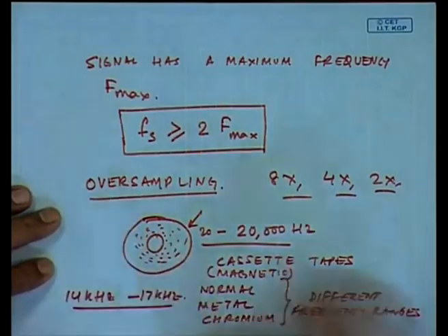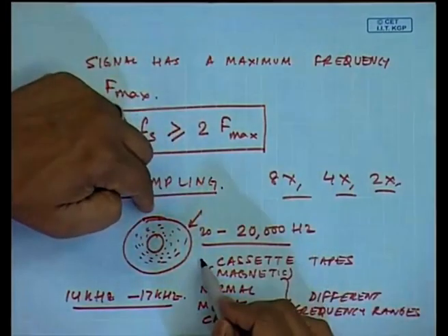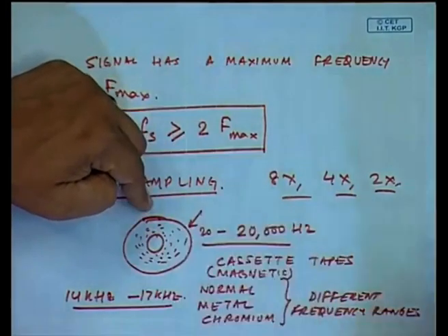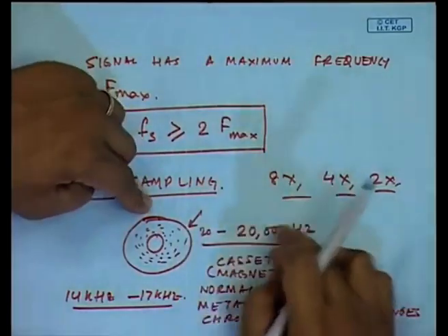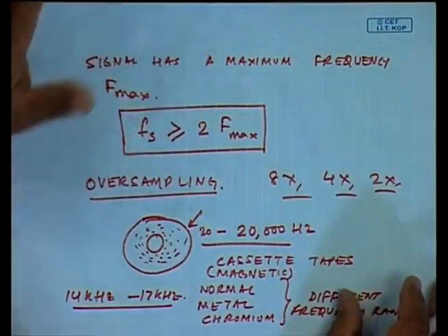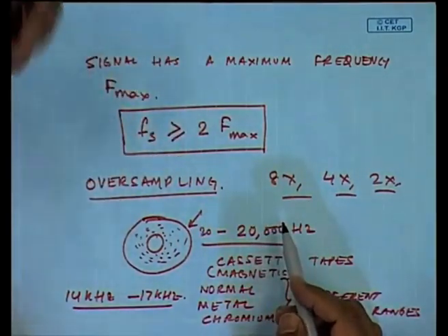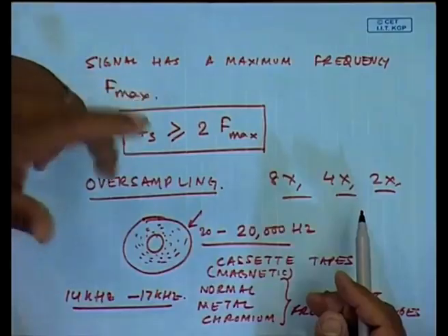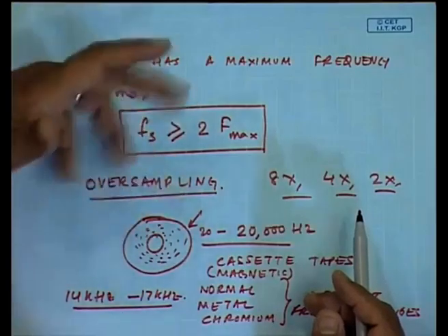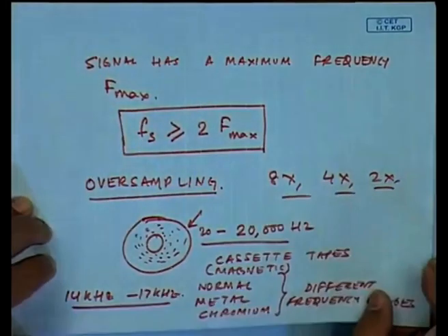But with the cassette tapes and magnetic tapes came the CDs, and in CDs you can faithfully store up to 20 kilohertz, sample this data digitally and get a very good reproduction of the high frequencies. So in a CD, when you listen to a guitar or a string instrument, you will hear it to be much clearer and more pleasant than on a cassette tape, because the high frequencies are reproduced in a much better way. So that all relates to the sampling frequency.